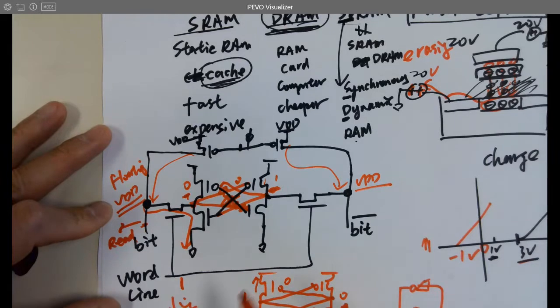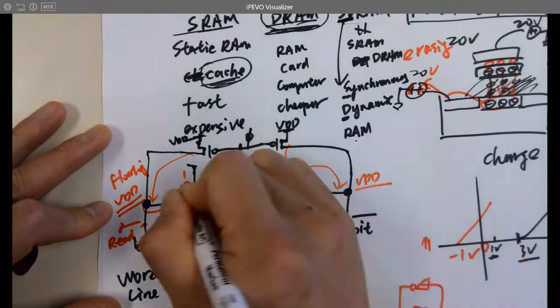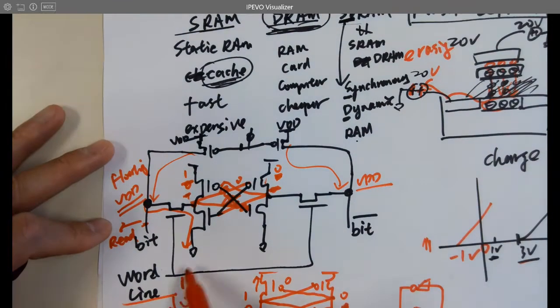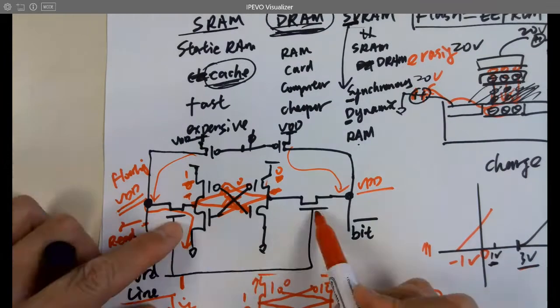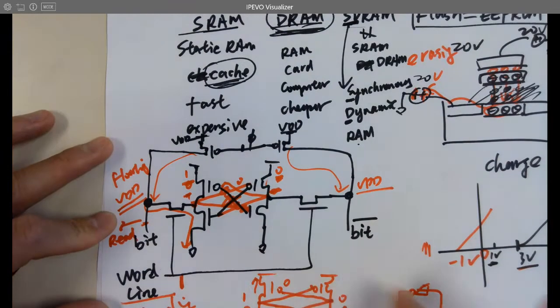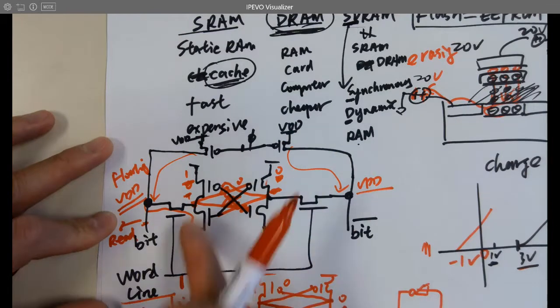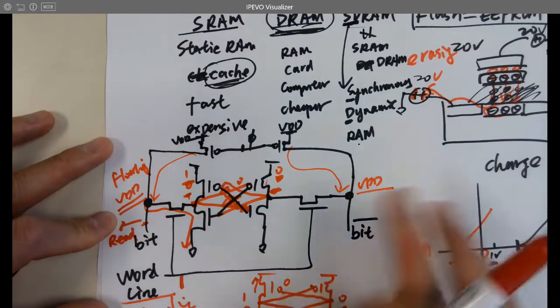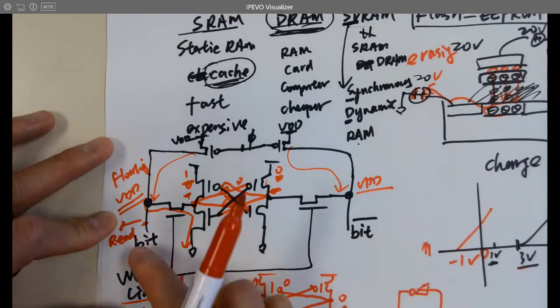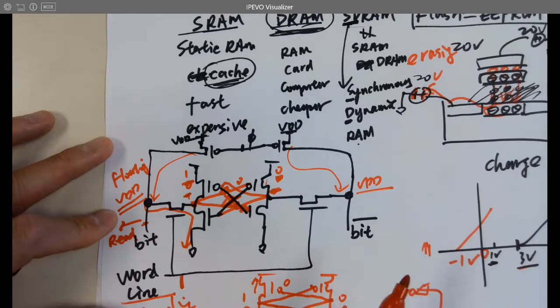Make sense? If you had a 1, 0 instead, what's gonna happen? When the word line comes, the decoder turns this on, 2 NMOS on. Don't look at this one yet. It's gonna be inverted because it's a latch. It's positive feedback. Whenever you got a 1 here, you got a 0, 0, 1. Right? We don't care about bit bar right now, just bit. We're reading bit.